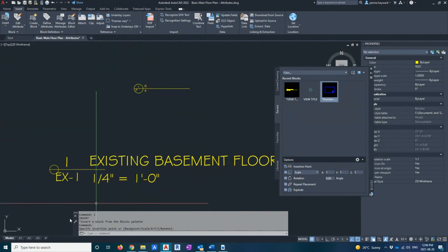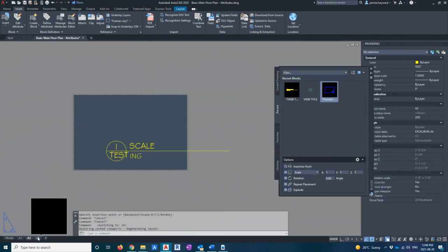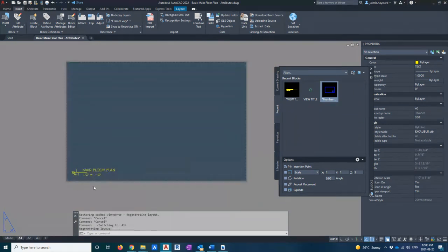So that's option 2. That works perfectly, because if I go into my next page here, just like that, it's there. Now it's still a little too large in my opinion. I'd rather it be about this size. This one's been redefined, so that is the same. So okay, I'm glad this happened in my recording. So just keep this in mind. When you make this change to the block, it makes it everywhere. It makes this change everywhere. So be very, very careful about this, okay?